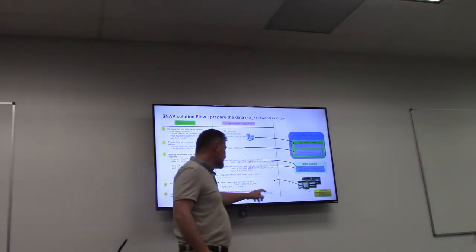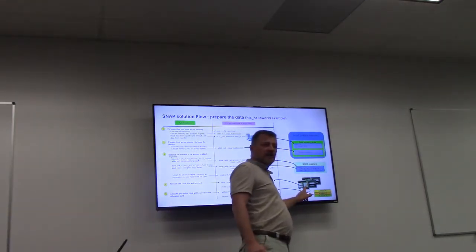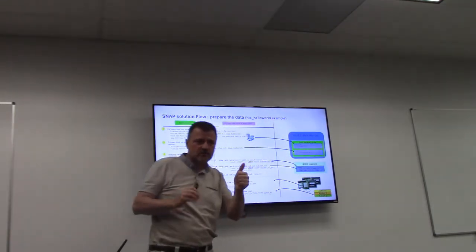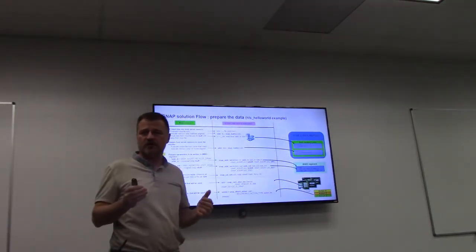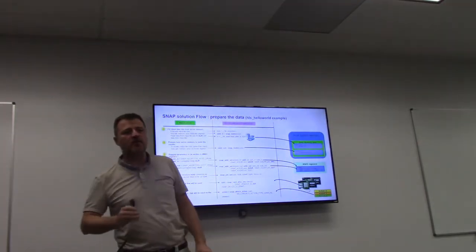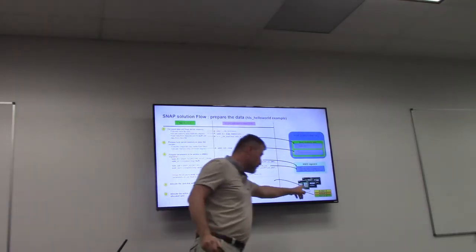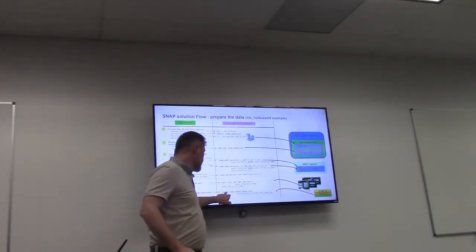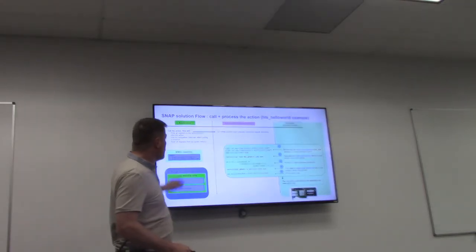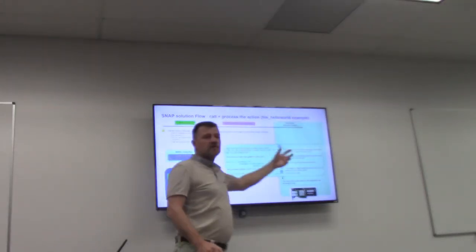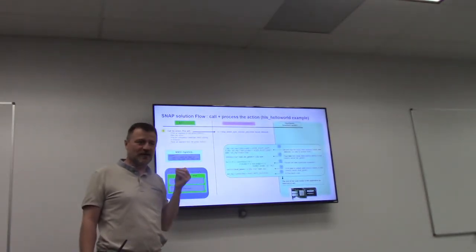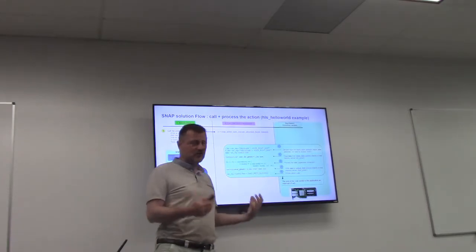We need to select the action that is present in the FPGA. The FPGA will say, hey, I have, so today, again, we support one action, but the structure is aimed at several actions. It says, hey, I have two actions, hello world and a specific mem copy. Which one do you want to use? I want to use the hello world, okay? So we get an action name, an action type. And once we have that, we will run this snap action. This is why we need a very small snap library on the processor side, okay? Because all these names need to be understood.